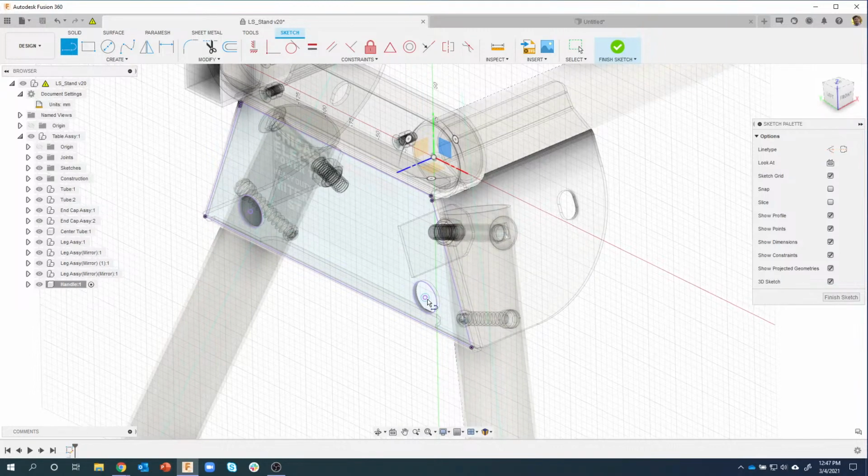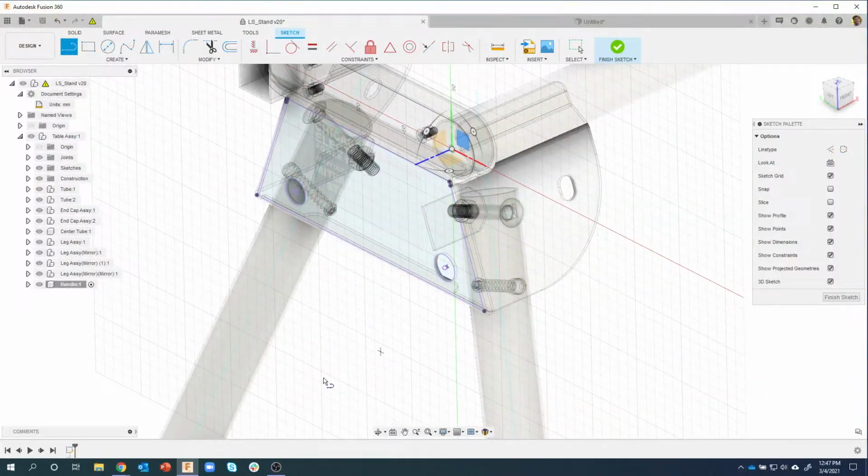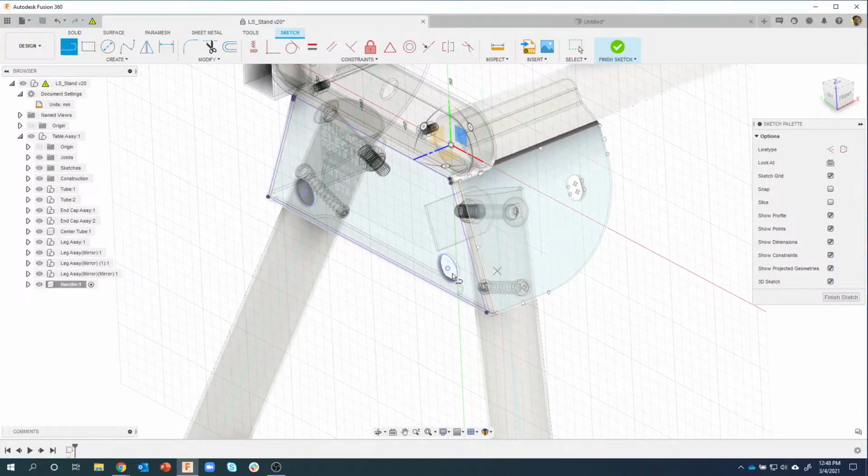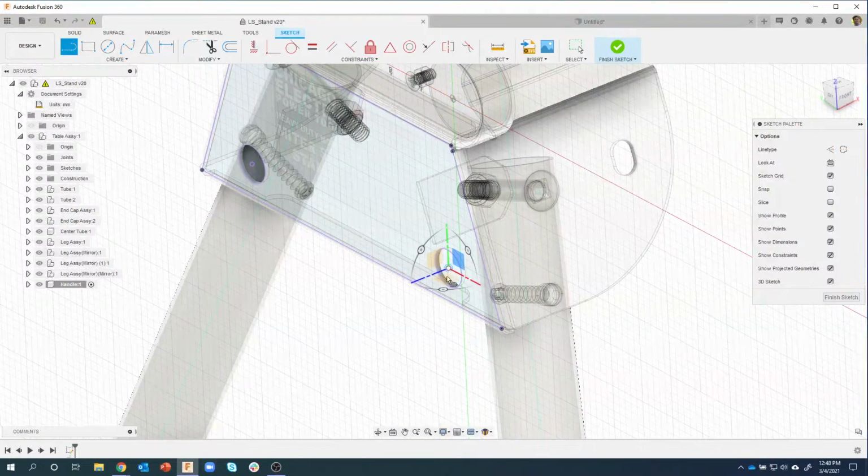But we want it on because we're basically going to draw how we want this handle to look coming off of this part right here. So 3D sketch is turned on. I'm in my line command. I could do the spline, but in this case we're going to do line. And it's going to catch that point. So watch what happens when I click there. This little triad jumps to that point, and it's allowing me to draw a line.